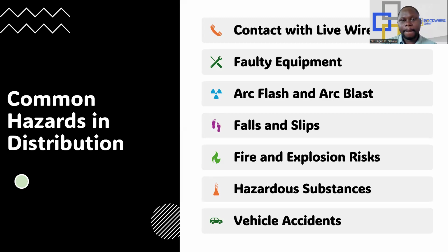I will double tag. Thank you very much. Who is that? Wasiu Adewumi. Thank you very much. You will double tag, so that when the person finishes work and comes to remove his own tag, your own tag will be there. The person will have an idea that you are also carrying out a task on that line.